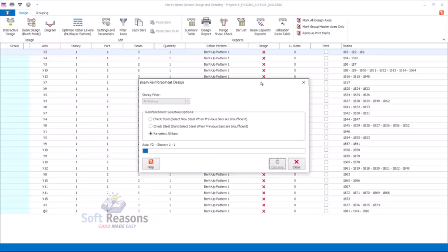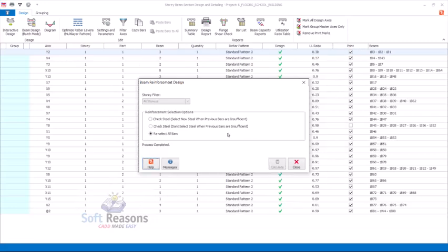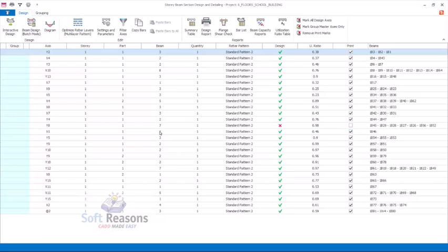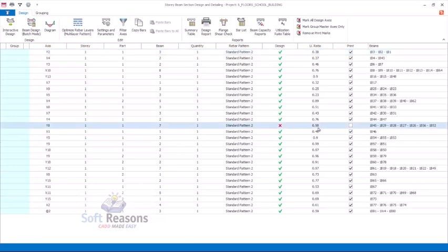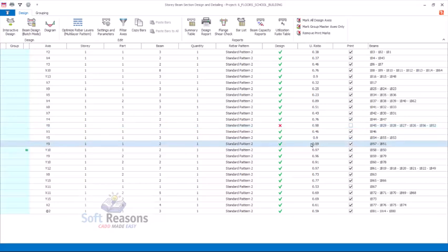We can also check the information content, design results right here, and then we will be able to know which of the beams is stressed, and then we see how we can apply some stiffness to the beam, to see that all of the beams pass design successfully. Click on the close option. Oh no, unfortunately we have this beam failing. All of these have actually passed very well. There's none more stressed except this one, which is stressed up.